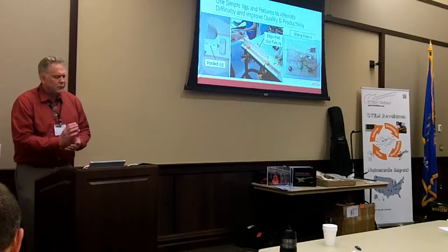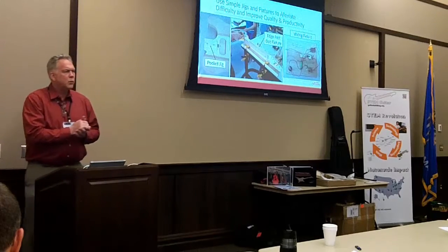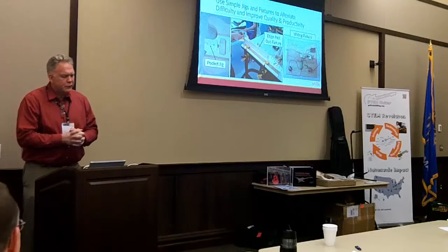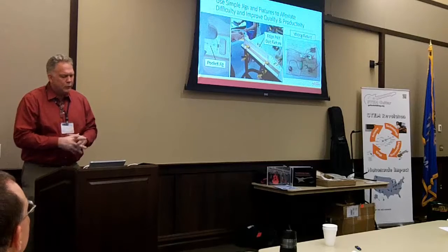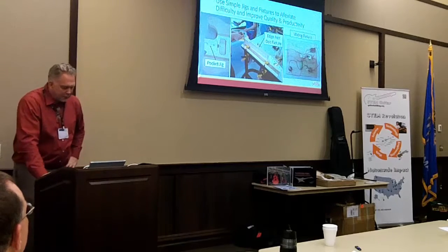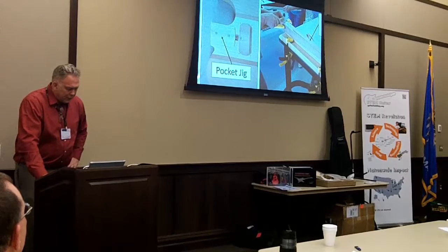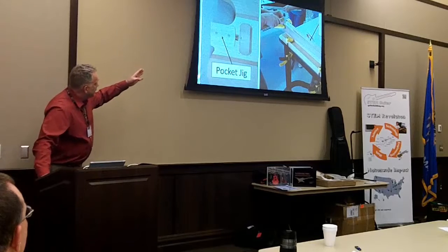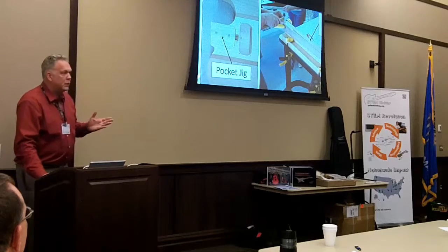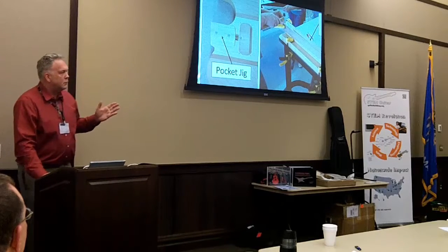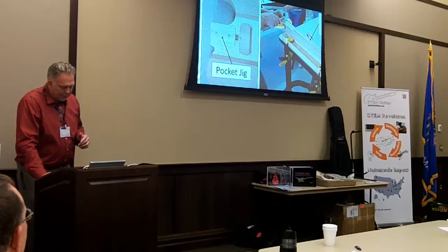Another thing we were looking for is a way to make things easier and less difficult. Simple jigs and fixtures alleviate difficulty and improve quality and productivity. Like for instance, when we're routering around these edges on the pocket, we got a pocket jig that we put in there to make it easy so that you don't end up routering off the edge too tightly when you run the router on it.